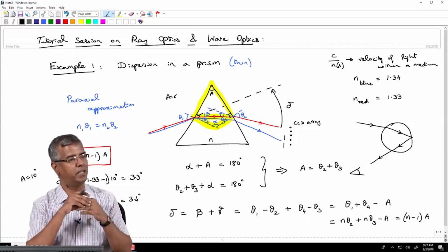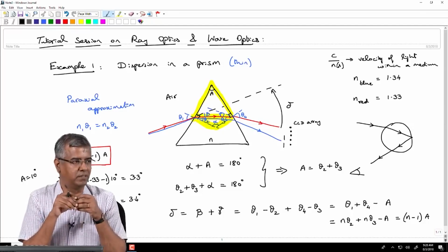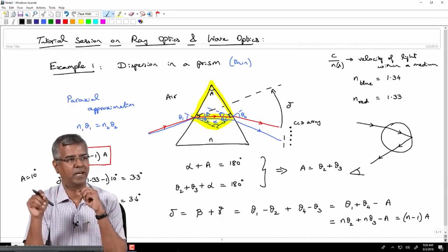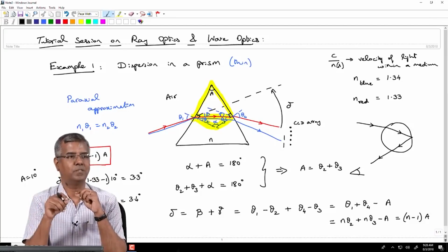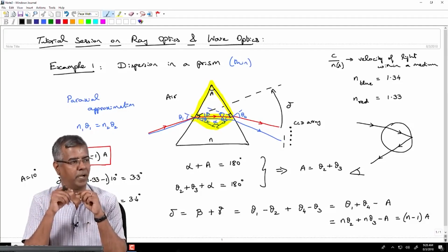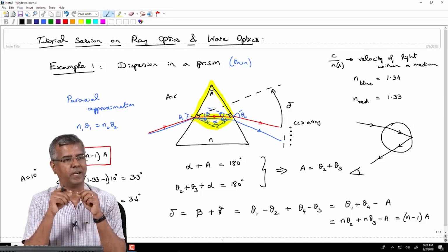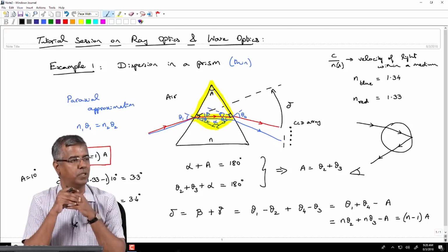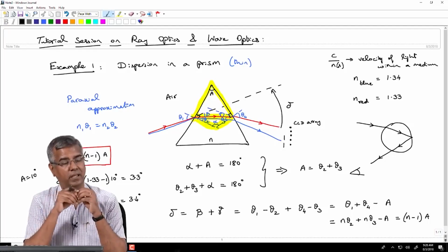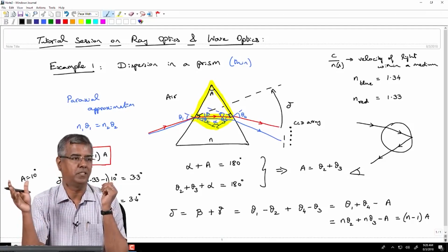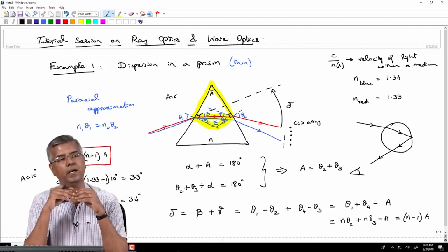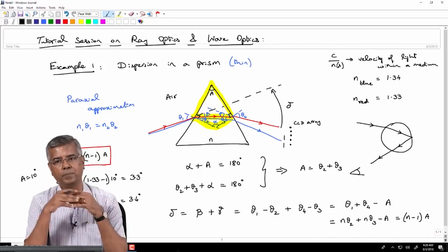And that is actually a major problem in optical communications. You can imagine this, it is going through a glass medium, and that glass medium actually provides different refractive index for different colors. So, if you have multiple colors going through that fiber, and we are talking about propagation over hundreds of kilometers of fiber, then all these colors separate out.